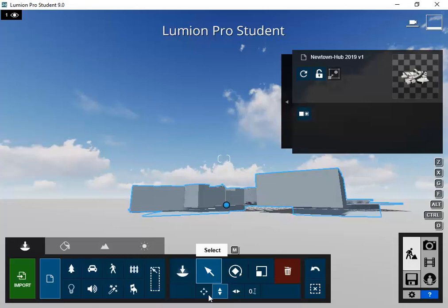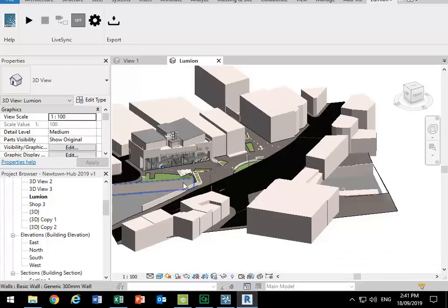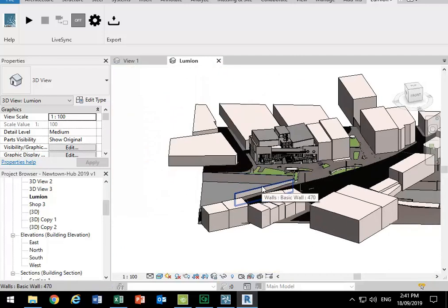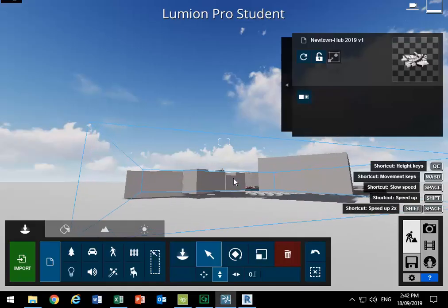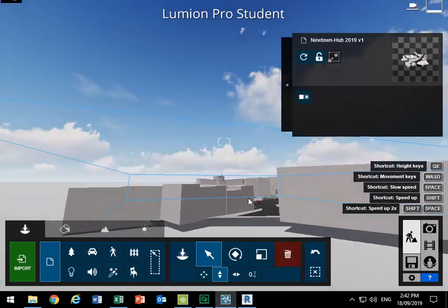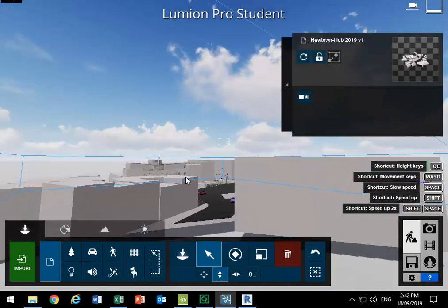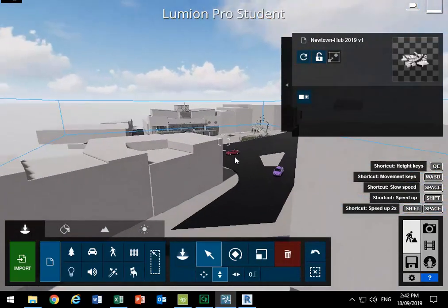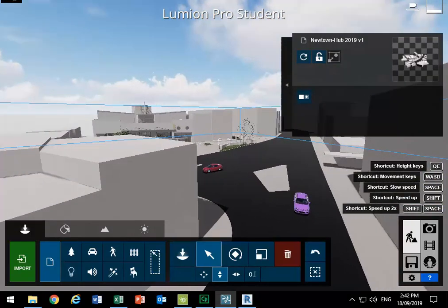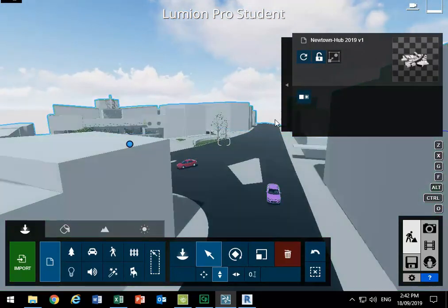So that's why it's better to make the ground surface like I have here in Revit. Use a topo surface to make the ground, and then in Lumion you'll get that. So here for the roads and all that, the things surrounding the site, that's much easier. You can't do that really in Lumion because you can't model things in Lumion.